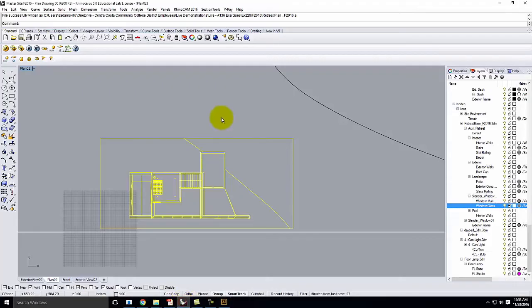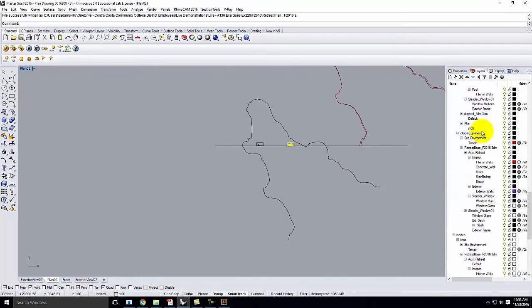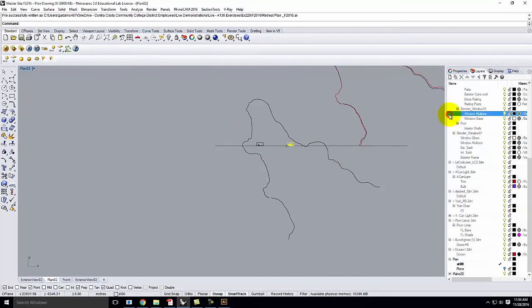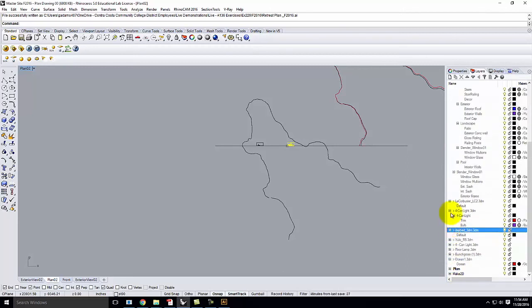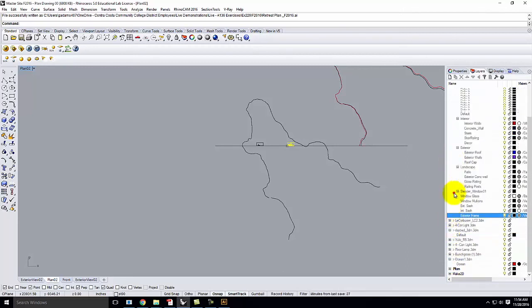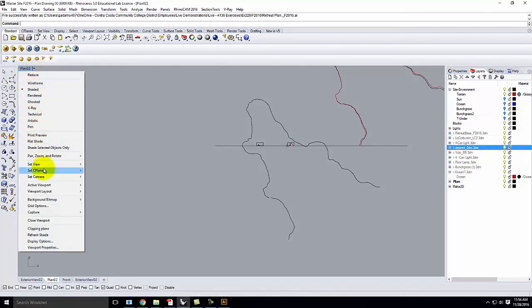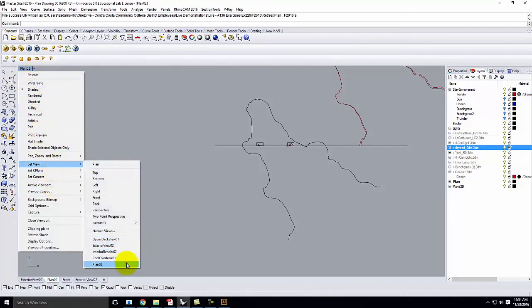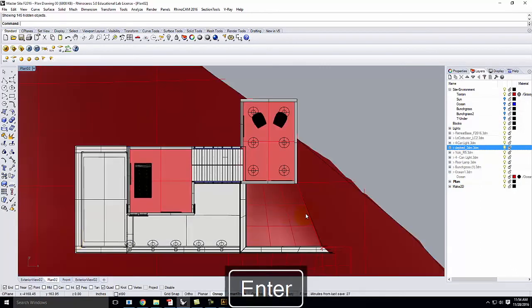So I'm going to go back to Rhino and make that export. So I'm done with the Make 2Ds, and I can actually come up here to wherever the start of the Make 2D is. We can make the whole Make 2D minimized. Let's minimize the rest of these, so we just don't have quite so much open. There we go. And we can come back to my Plan 2. Let me go back to Set View, Plan 2. I'm going to show so that everything comes back that I made hidden.